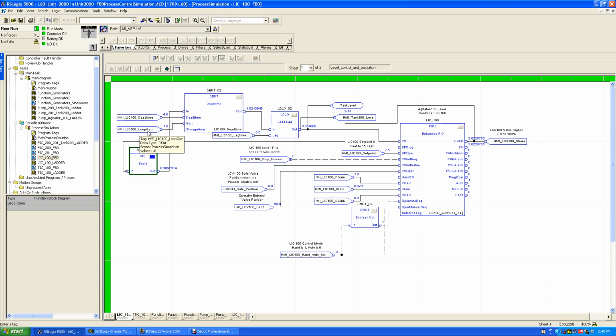You might want to go up to 2. It depends on how much your process gain would normally have. I think I have mine set to 1 for the level and 0.75 for the temperature for a gain. Then we come out of the dead time.